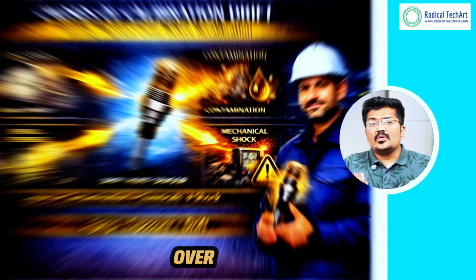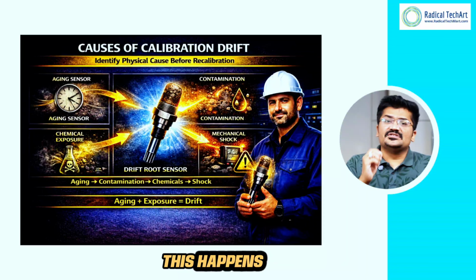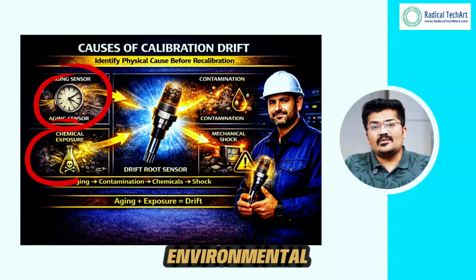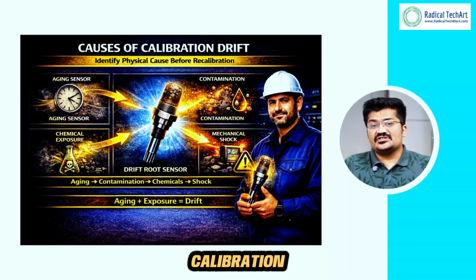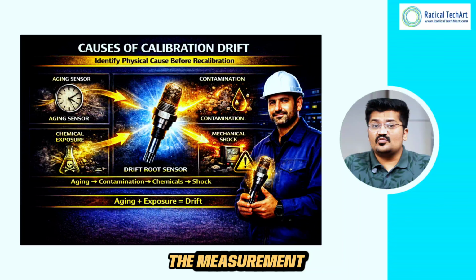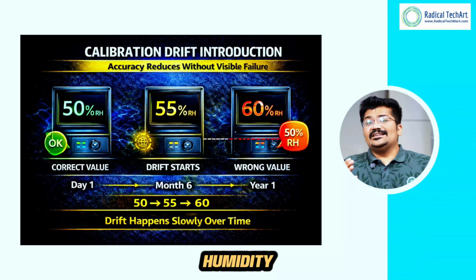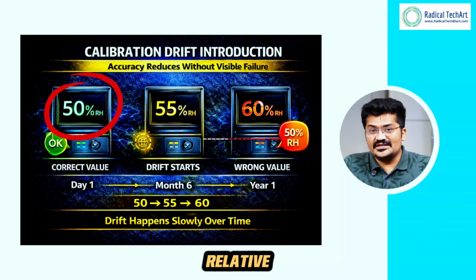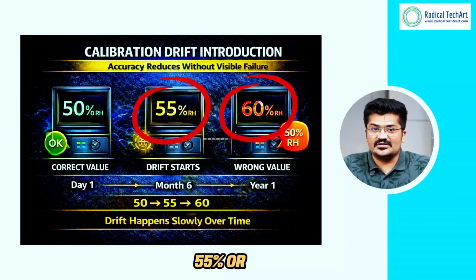Another issue engineers encounter is calibration drift. Over time, some sensors may slowly lose accuracy. This happens due to sensor aging, environmental exposure, and mechanical stress, and when calibration drift occurs, the measurement value gradually becomes inaccurate. For example, a humidity sensor that should read 50% relative humidity may start reading 55% or 60%.